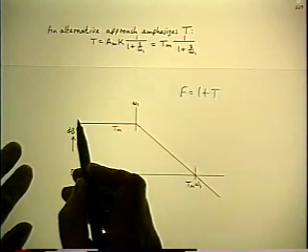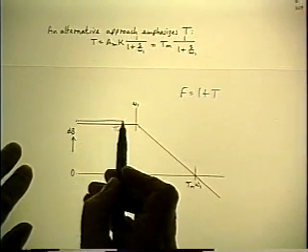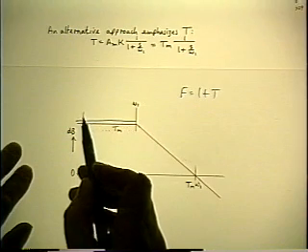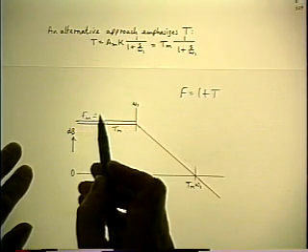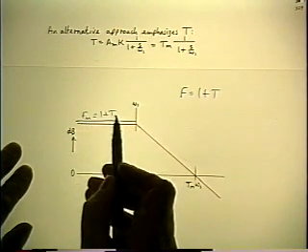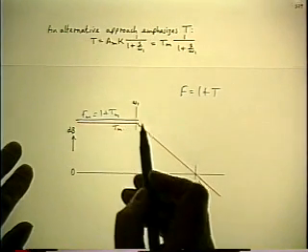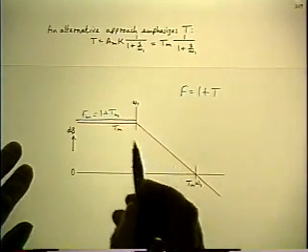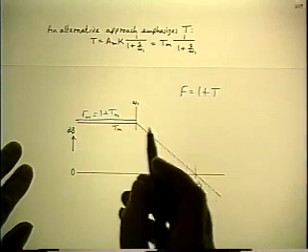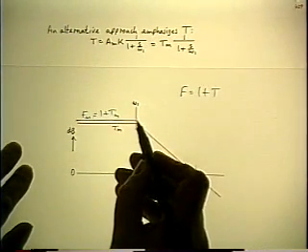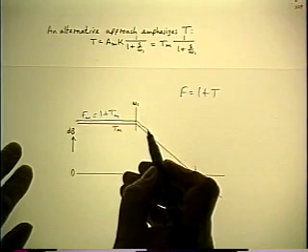So I draw another line down here just a little bit above this one. I label that one Fm for midband value is 1 plus Tm. As T goes around the corner, F will go around the same corner because it's still just a shade bigger than T, as long as T stays large.